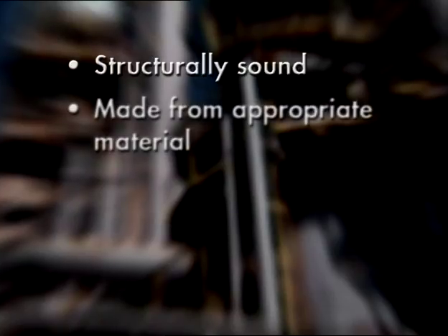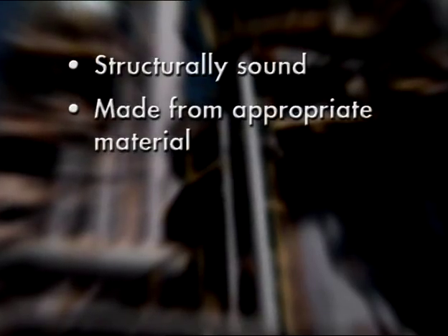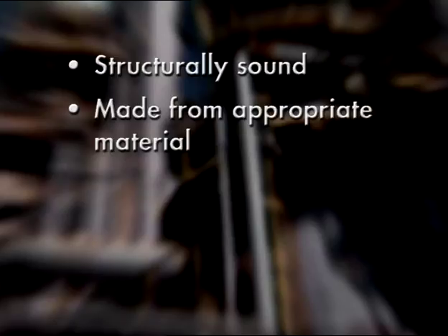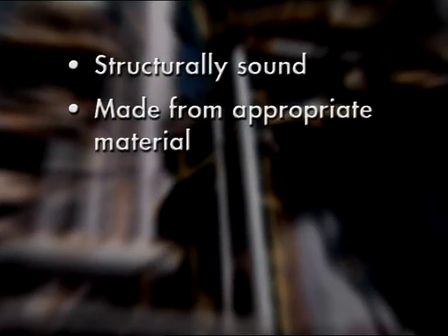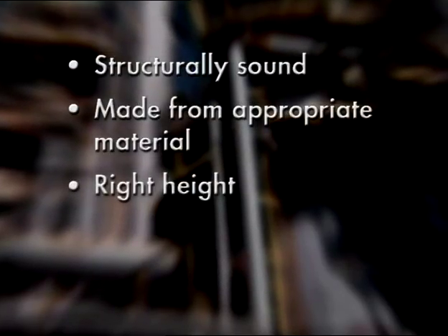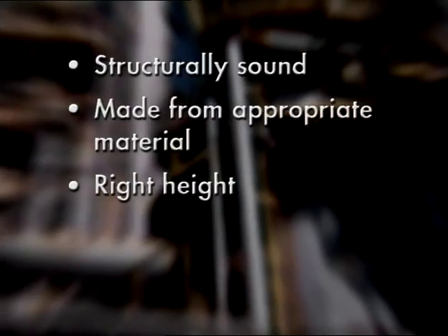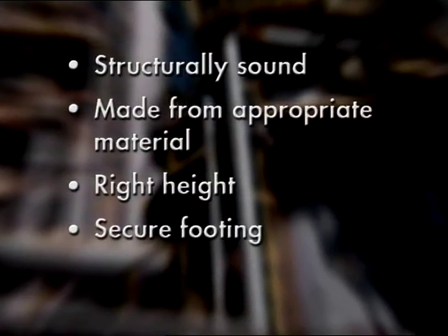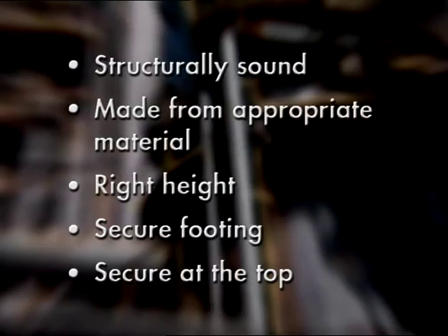The key safety points to consider are: the ladder is structurally sound. The ladder is made from appropriate material for the job task. For example, a metal ladder should not be used near electrical sources. The ladder is of the right height. It has a secure footing, and the ladder is secured at the top.